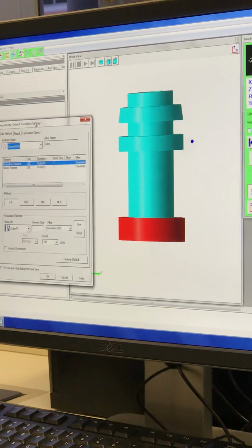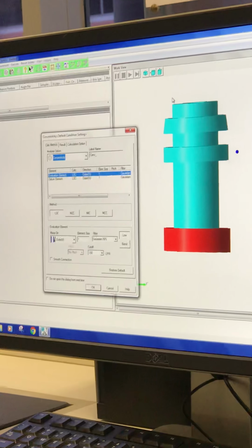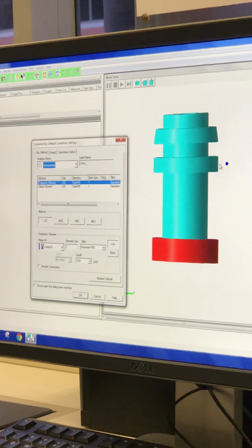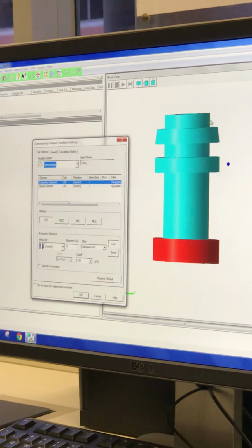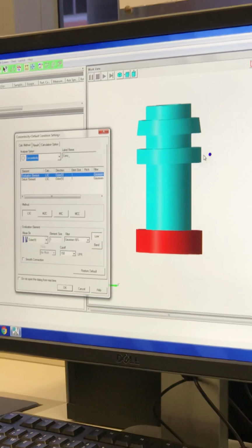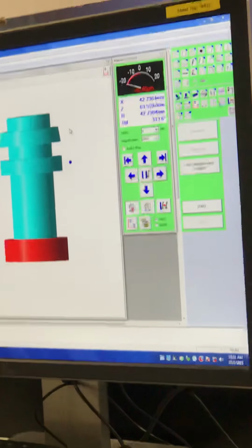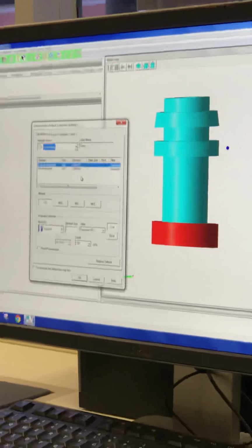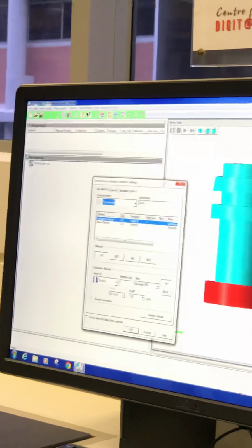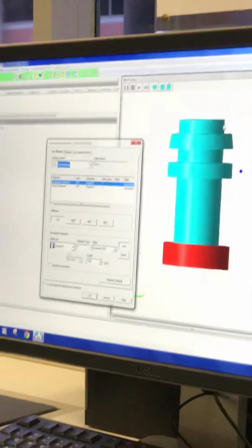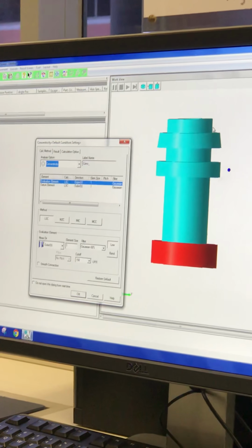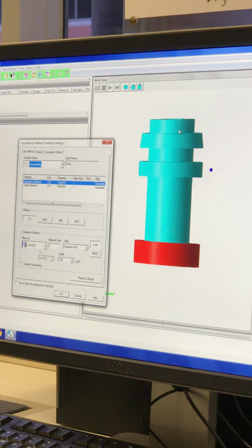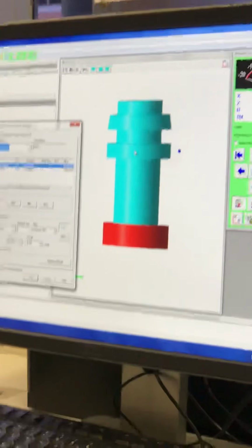Please listen here. You need to measure this diameter at the top. Another diameter will be the datum, so you need to measure this at the middle. So you measure this with respect to A. Clear now? There are two elements. The datum A is here, and the concentricity to be measured is here. With these two circles, you can analyze the center point, whether it is in the center point or the distance.